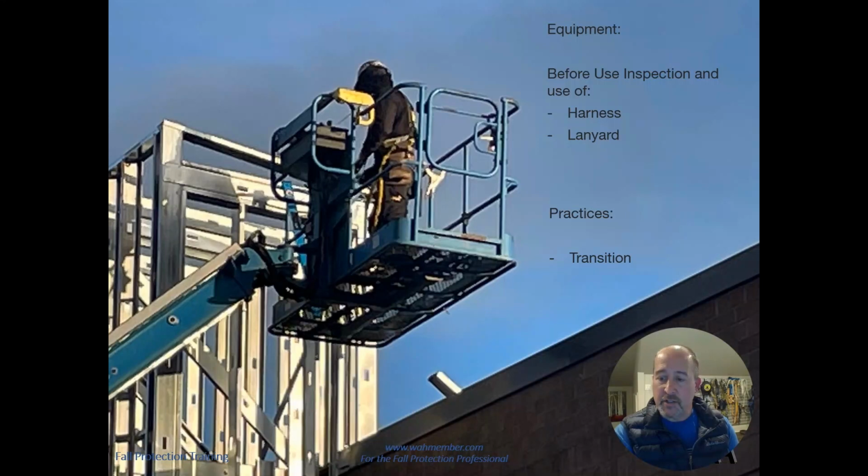They don't have to exercise any judgment in regards to clearances or anchorage selection, as all of that is done for them. So the training event is really going to be limited to the donning and wearing of the harness and where to connect the lanyard, or SRL if that's the piece of equipment that's being used, and how to adjust it as short as possible.